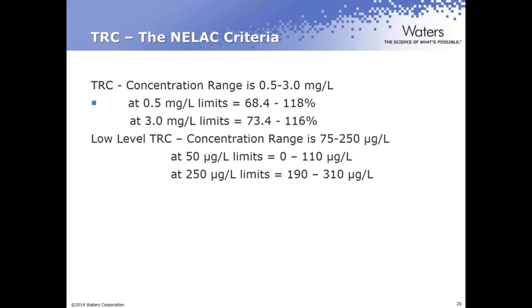So whether we're running a sample at a lower level or at a higher level, since the sample is being diluted for the most part to meet the range of the meters, the recovery is generally similar. The data that's been collected is similar regardless of the concentration range, and it's really method specific and not analyte specific for chlorine.